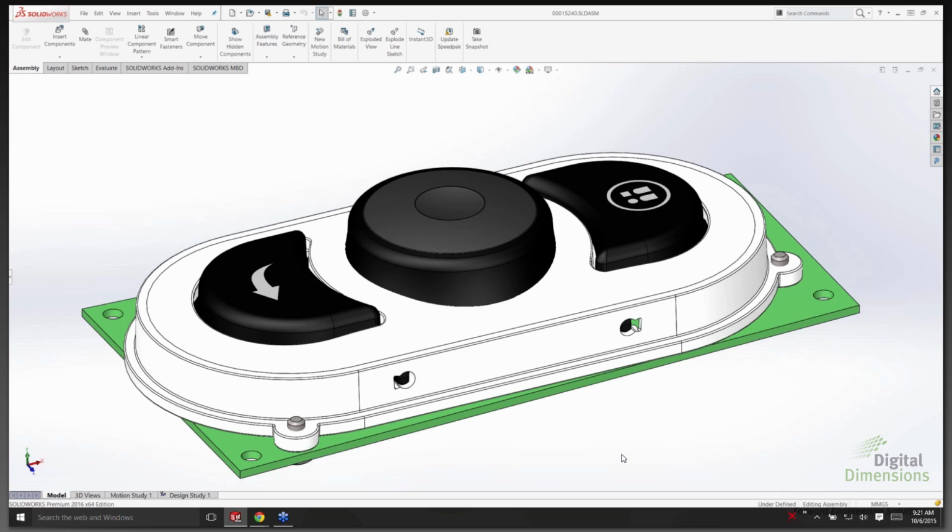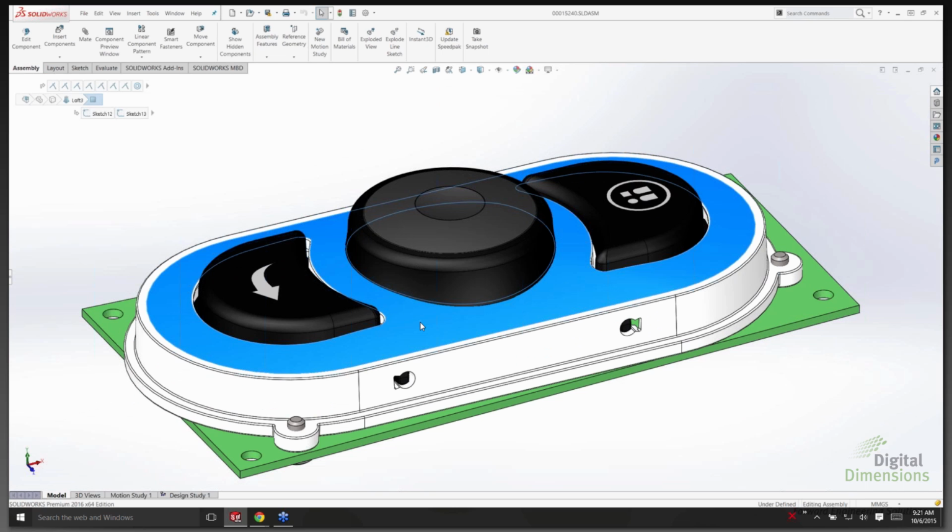I'm going to repeat it a couple times just so you guys can remember this, but this new breadcrumb feature is something that will allow you to access these different components of a feature or a part or an assembly simply by selecting this icon. And you'll notice in the top left-hand corner, we now have this breadcrumb feature that gives me these different selection sets based on what I've selected. So I've selected the face right now. I have access to that face itself. I have access to the components driving that face, so this loft, or even the sketches that are driving the loft itself, the body, the part, or even the assembly.